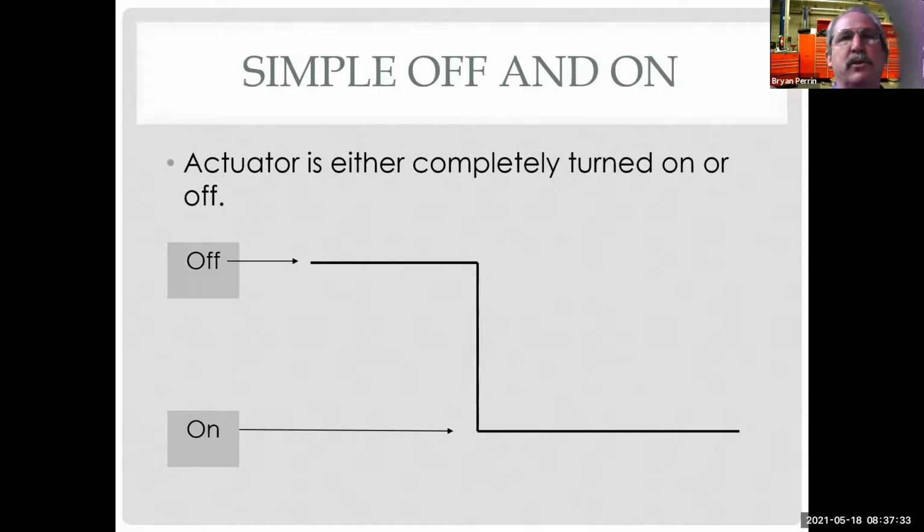Very few manufacturers do that. Honda and Chrysler both do. They like high side control. Other manufacturers will do it on occasion, but Chrysler and Honda are both known for it. But most manufacturers, we're going to see power on the control wire when off and then ground when it's on. So this is simple on and off. We do have some circuits out there like that.